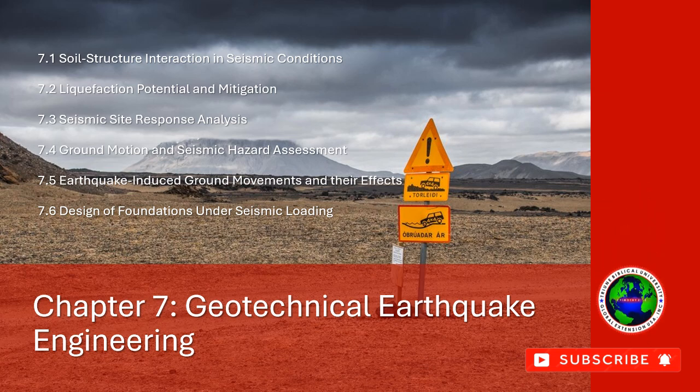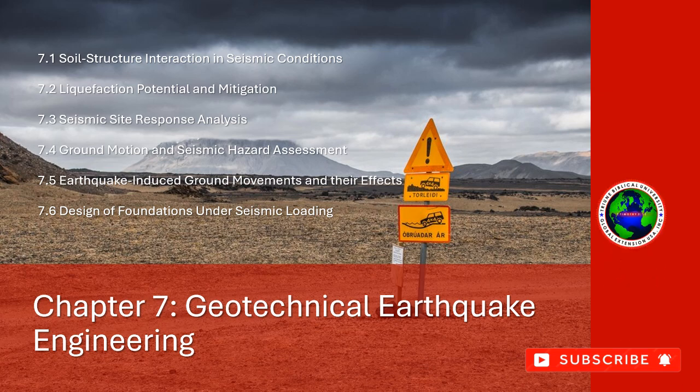3. Duration. The duration of shaking refers to the length of time over which the ground motion persists. Longer shaking durations can result in more extensive damage, particularly in structures and soil that experience cumulative degradation over time.